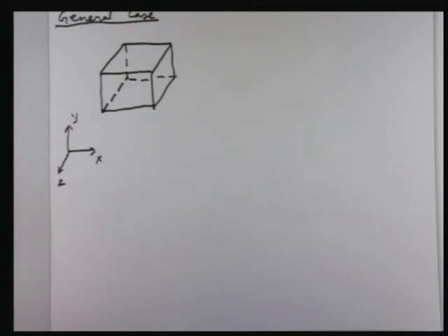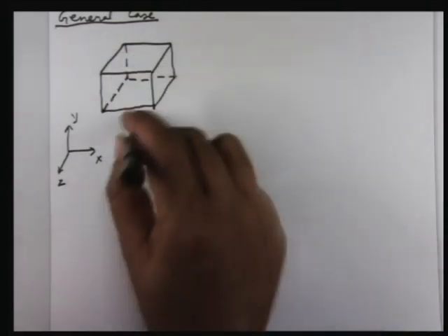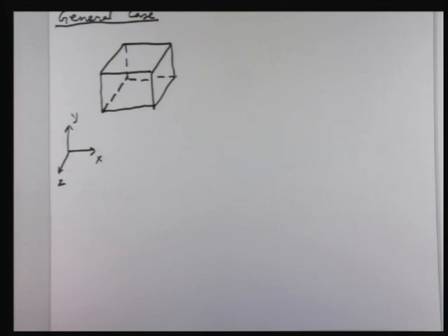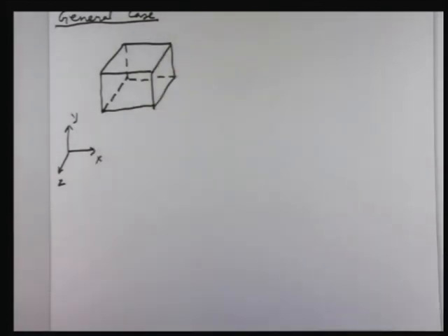Even if the fluid is moving and we want the net force due to the pressure, the pressure force is acting normal anyway. If the fluid is moving, there will be other forces which you have to consider. So the pair which is perpendicular to the Y direction will not contribute to the X direction force. Similarly, the pair which is perpendicular to the Z direction will not contribute to the X direction force.